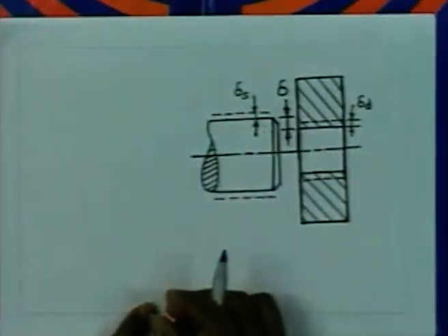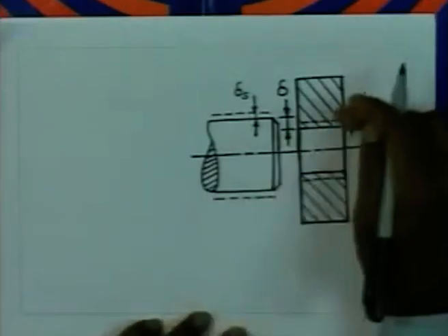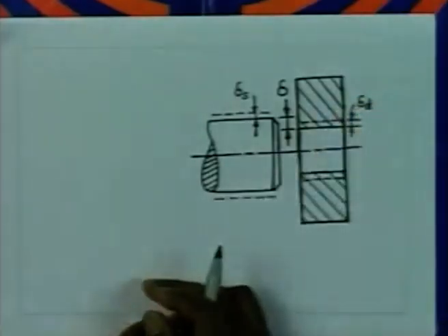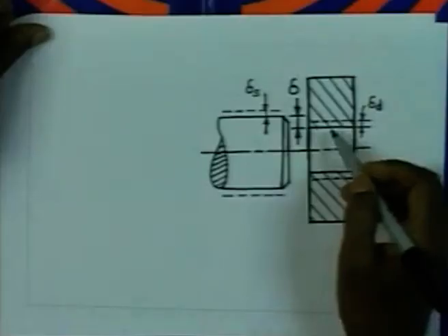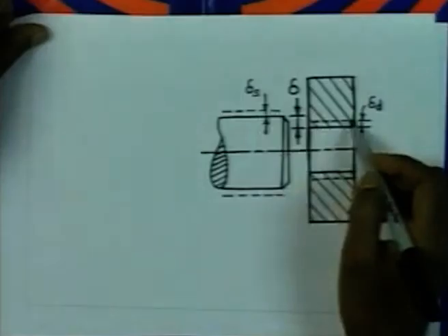So, how do we find out the rotation which is going to make the disc free of the shaft? That is the point we have to look into. Imagine when the disc is going to be loose on the shaft. As the speed increases, the shaft is also increasing in dimension, so also the disc is increasing in dimension.